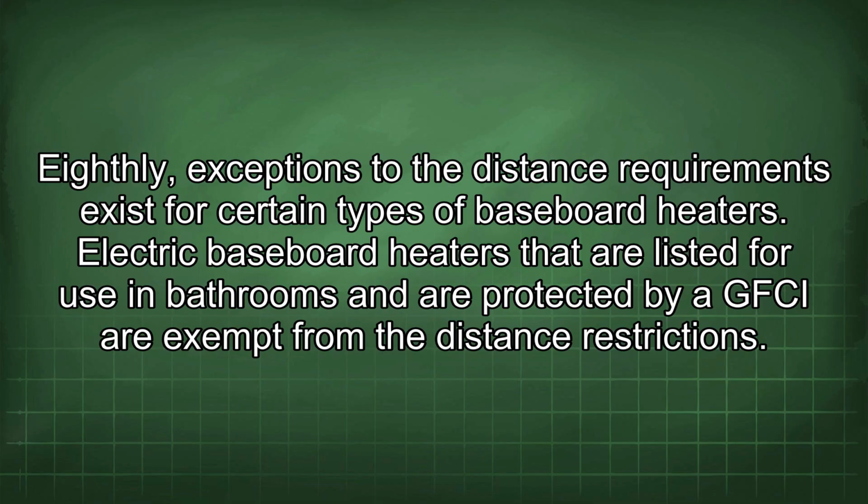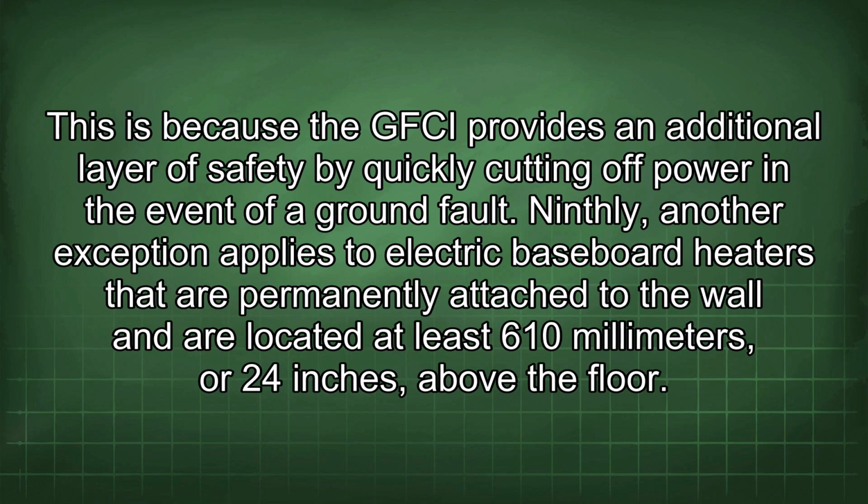Eighthly, exceptions to the distance requirements exist for certain types of baseboard heaters. Electric baseboard heaters that are listed for use in bathrooms and are protected by GFCI are exempt from the distance restrictions. This is because the GFCI provides an additional layer of safety by quickly cutting off power in the event of a ground fault.